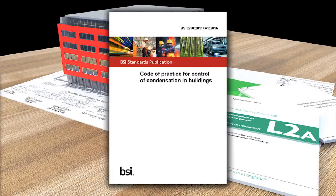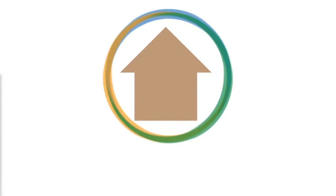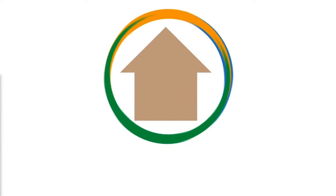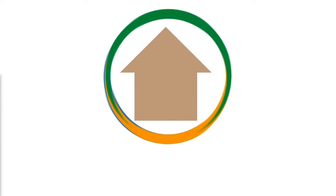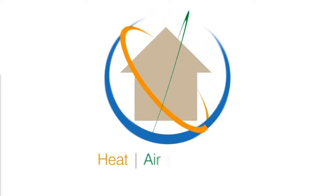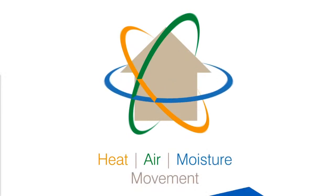It is, however, clear that for more complex scale structures, a more dynamic and extensive approach enabled by using the latest software and improved computing power is not only desirable but more widely achievable than ever. Between WUFI moisture assessment and the more complex energy modelling enabled by modern BIM software, it's now possible to model the balance of heat, air and moisture accurately and hence to design and specify with much finer tolerances. This helps ensure a cost-effective and robust building that remains fit for purpose for many years.